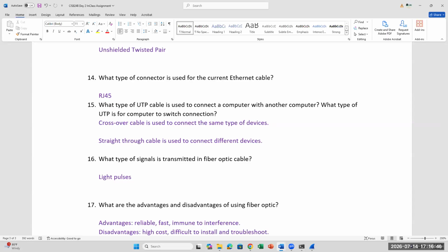Okay, there is a line across the connector. That line is pressed down onto the cable to hold it in place. So once you crimp it, that crimp line is going to press down on the plastic coat of your cable.